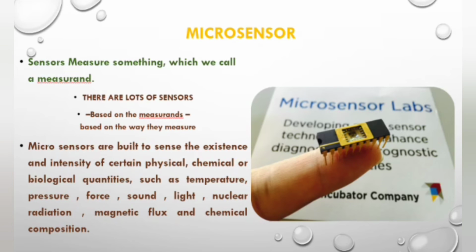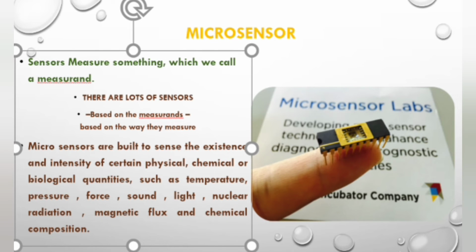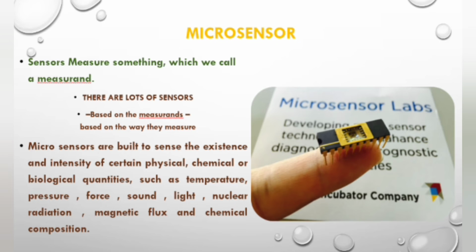Some of the MEMS sensors are MEMS accelerometers, MEMS gyroscopes, MEMS pressure sensors, MEMS magnetic field sensors, etc. MEMS accelerometers are used in smartphones for various controls, including switching between landscape and portrait mode, anti-blur capture, and pocket mode operation. There are generally two types of MEMS accelerometer: variable capacitive and piezoresistive.